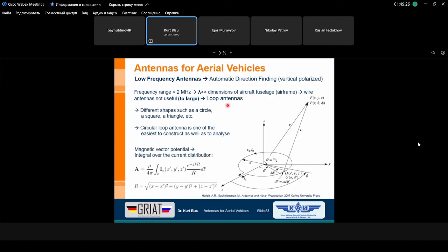This also, we could apply this. The problem is, in such a short dipole, that the radiation resistance of such a wire antenna, of such a dipole antenna, goes very, very fast to a very small value. Very small value means we have a lot of problems to use this signal coming out from such a dipole in connection with a receiver.